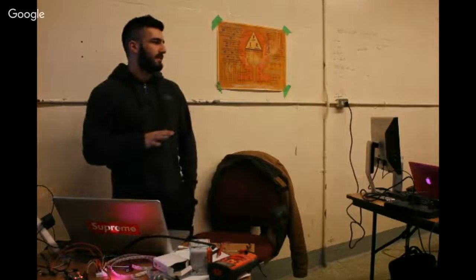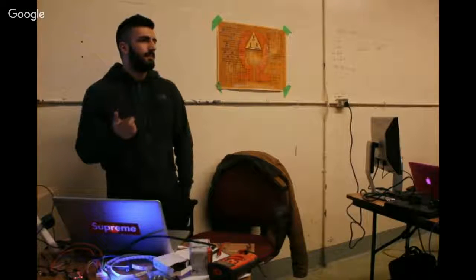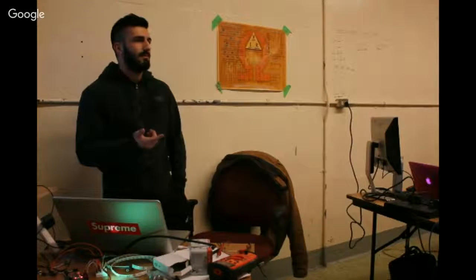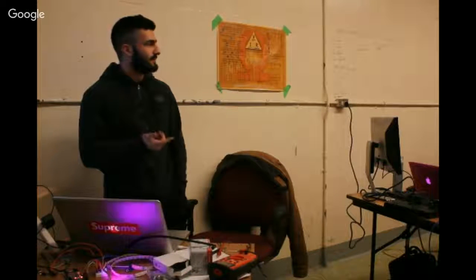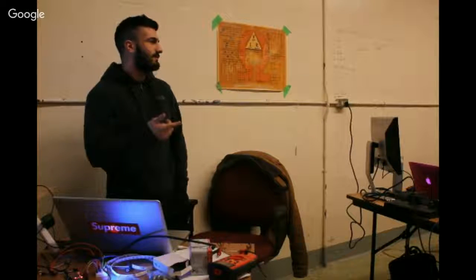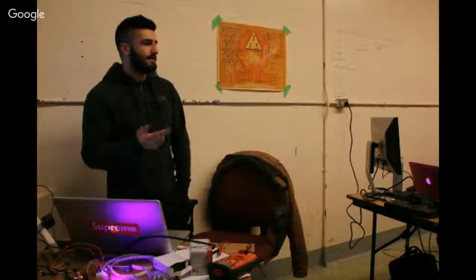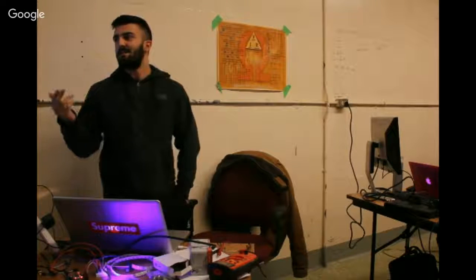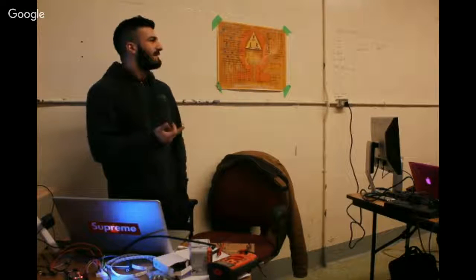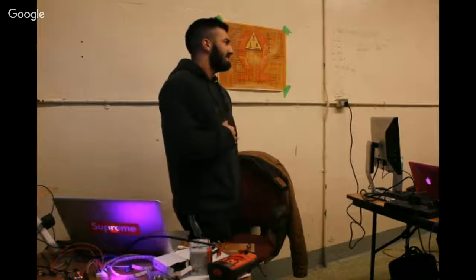Basically the whole program stops and delays for that amount of time. But we don't actually want it to stop. We want it to keep sensing and making sure that, once this delay is over, is there motion in the room? Do we want the fan to turn back on? Yeah, am I saying this right? Yeah, I think so. The delay statement gets you a blocking delay.